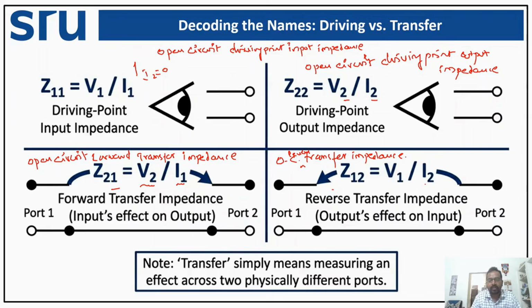For example, in amplifier design, sometimes we want to use strong coupling to transfer signals effectively. But in other situations, such as noise, oscillations or filter design, we may want weak coupling. Thus, understanding the physical meaning of Z parameters helps engineers make design decisions, not just perform calculations. So, whenever you see the Z parameter equations, do not think of them as abstract symbols. Instead, think of them as describing how energy or signal transfer occurs inside the network. This physical interpretation makes the mathematical model very meaningful and easier to apply in real engineering problems.